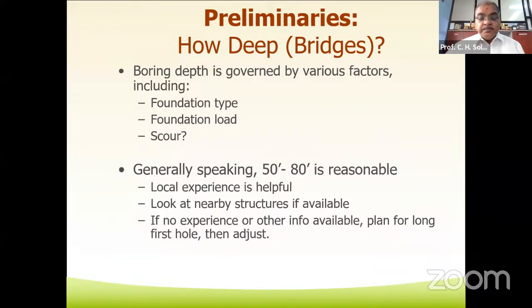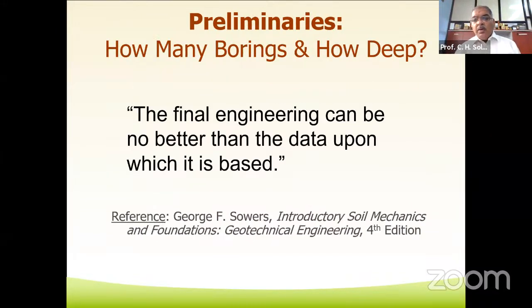experience is helpful. Look at the nearby structures if available, and if no experience or other information is available for the particular site, plan for a long first hole and then adjust. How many borings, and how deep will you go?